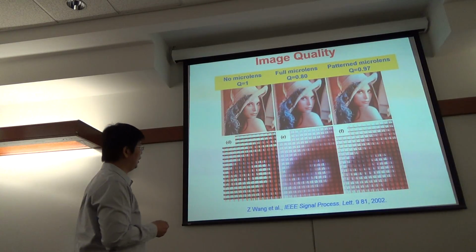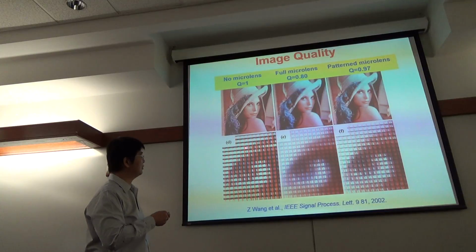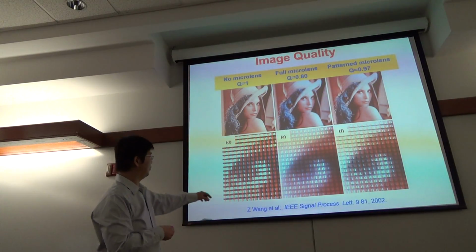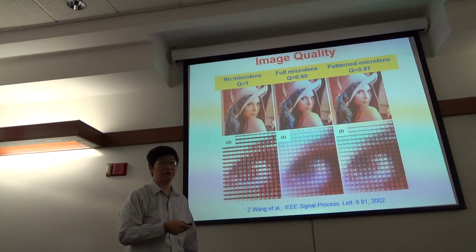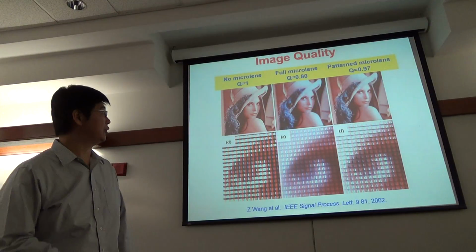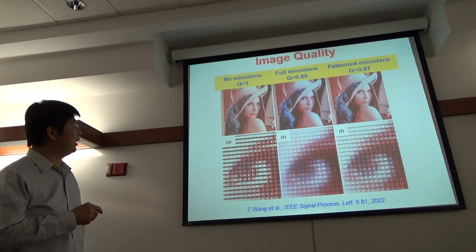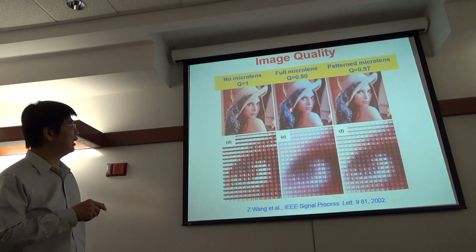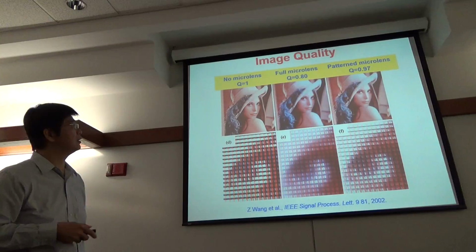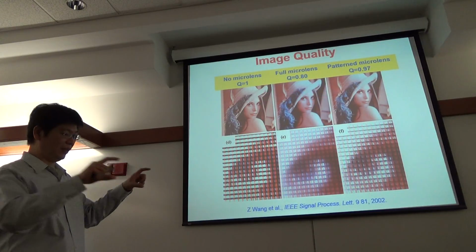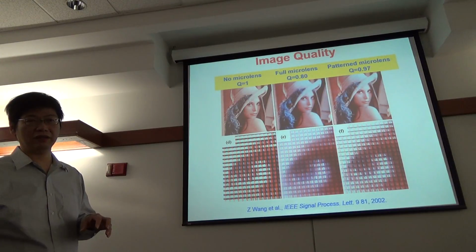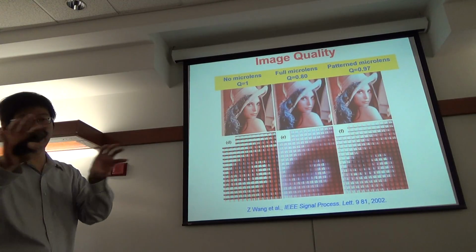We took the picture under the optical microscope. You see there's a black region over here. That is the TFT region, so that's the aperture ratio. After that, you put the microlens on the display and take the picture again. Then you transfer it to grayscale, and they can calculate, because it becomes many pixels.